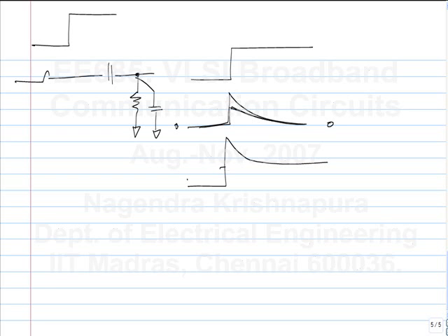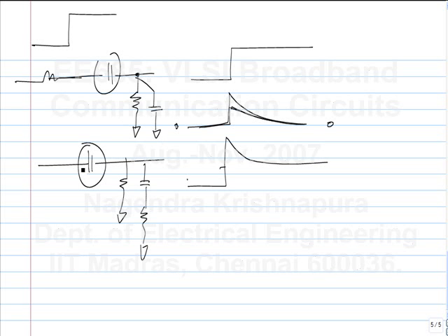See, if you add anything in series, if you have a series capacitor, it will block DC. If you have a long, oh, you mean you want to do this? Once you have a series capacitor, if you have a long string of ones, the output will eventually discharge to 0. Because the DC gain of something like this is definitely 0, isn't it? So what you want to do is, this is effectively the response that you want to get.